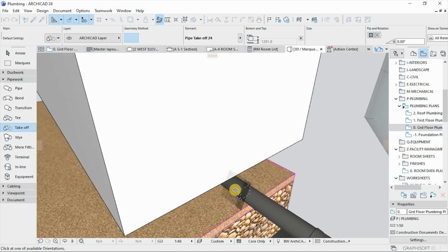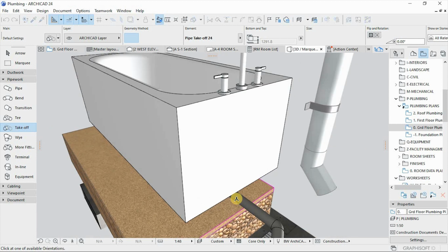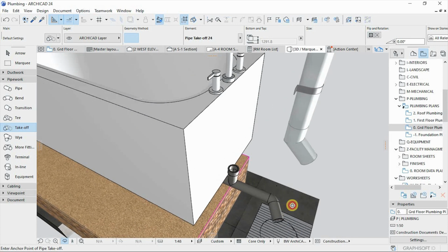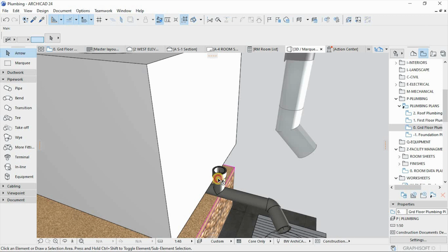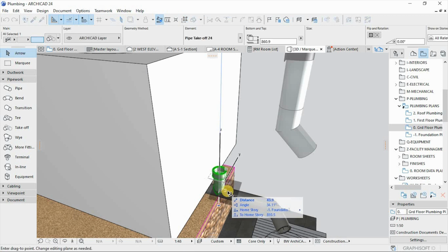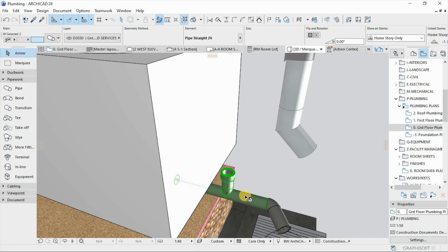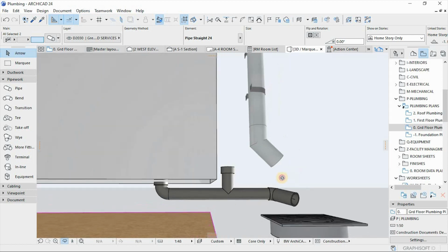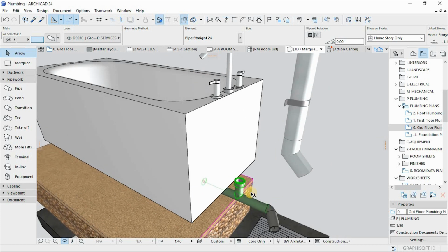It will indicate these arrows to show the direction of your pipe. In this case, you are going vertical, upright. So I'll hover the mouse up so that it can get the direction, and then click. There we go. Now we have the connection point here, and it's flexible, it's editable. You can also drag it, move it where you want, like so. It will snap to the mother pipe, and then we're gonna have another pipe going up.